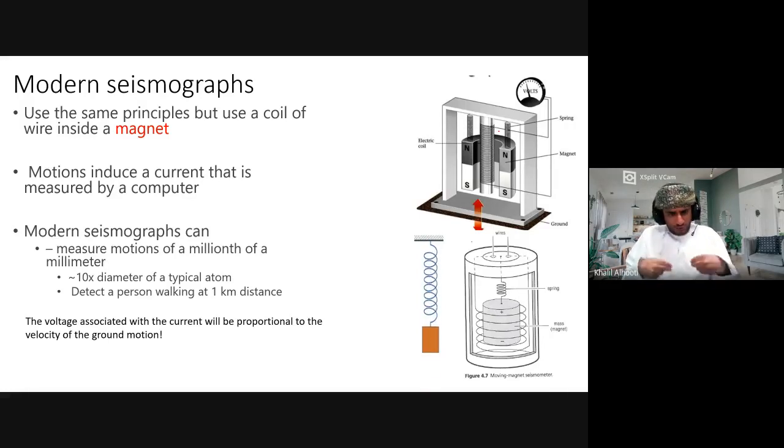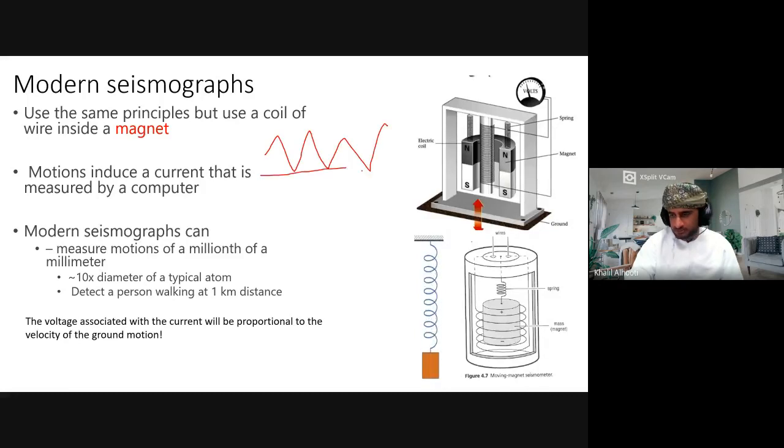There is something I would like to explain slightly. Whenever we are recording, there is no computer which can record or save data continuously. Everything in a computer is digitized, in digital format. So there is a terminology in computers called sampling. Let's say my waveform is coming as a continuous waveform, and this is time and this is amplitude. I say, what is the amplitude at that time? You say that's it. What's the amplitude at time 1, time 2? You can read it. But then I say, what's the amplitude in the middle? You can go and say that's it. But what's the amplitude in here? You say that's it. But you cannot go on indefinitely.